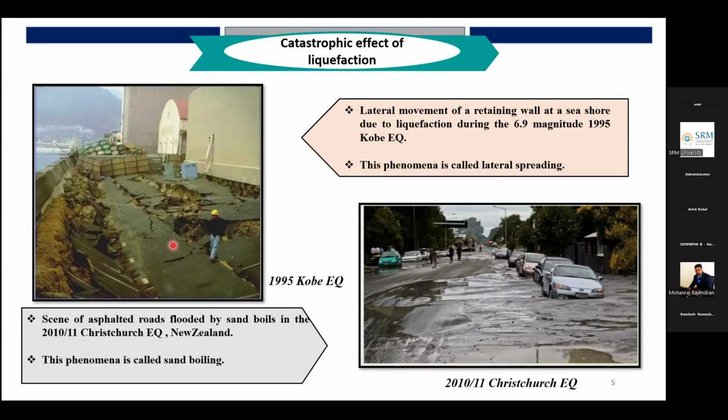instantly because the period of earthquake shaking is very few seconds. Within those few seconds, the built-up pore pressure is not able to dissipate, and thereby the pore pressure tries to reduce the effective overburden pressure of the soil, and the whole system is almost like a liquid state. So whatever structure is placed on that kind of soil, buildings are subject to collapse.